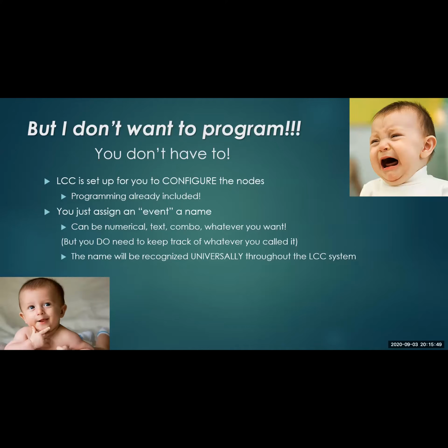LCC is more set up to configure the nodes. The best analogy I can use is when you put a decoder into a locomotive, you don't actually program the logic in there. You just go and set your CVs. I want this bell, I want this horn, I want this speed curve, and then it runs with it. So you're configuring it. Does that make sense? You're really not writing code. In LCC, that's the same thing. You don't really write the code.